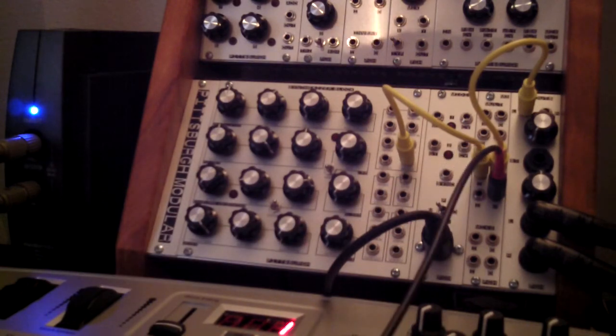This will allow us to view on the computer monitor the shape of the waveform and switch over to the spectrum analyzer and look at the harmonic content of each waveform. We'll also talk about the basic properties of sound, of frequency, amplitude, and timbre. Talk about what those mean in relationship to the way a waveform sounds the way that it does.